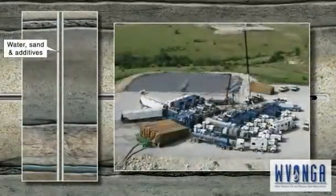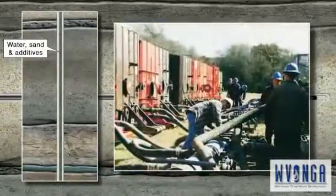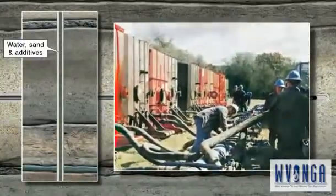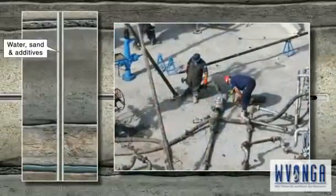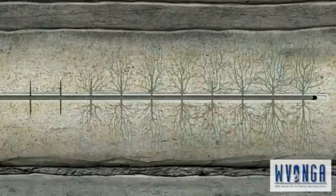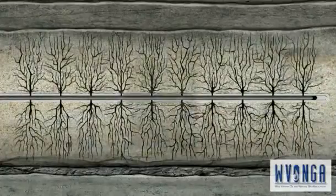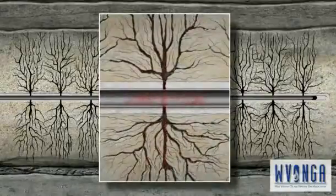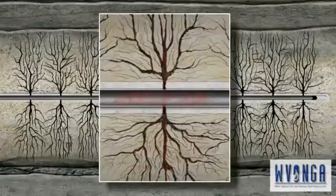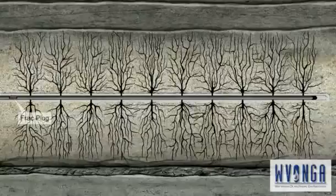Known as hydraulic fracturing, this is a process where water, sand, and additives are pumped into the wellbore and down the casing under extremely high pressure. As the mixture is forced out through the perforations and into the surrounding rock, the pressure causes the sandstone to fracture. This creates a fairway connecting the reservoir to the well and allows the released gas to flow to the wellbore. Next, a temporary plug is placed at the heel or left side of the first stage frac.